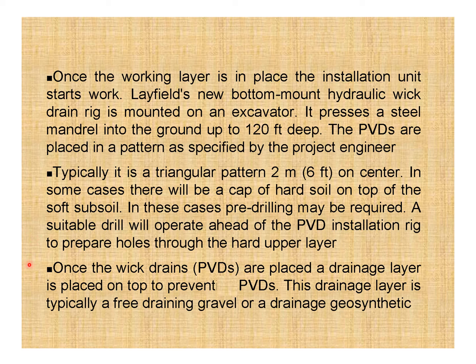Once the wick drain PVDs are placed, a drainage layer is placed on the top. So this point must be noted that once the wick drains are placed, a drainage layer is placed on the top. This drainage layer is typically a free draining gravel or a drainage geosynthetic.